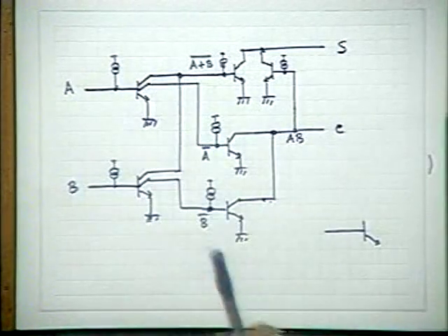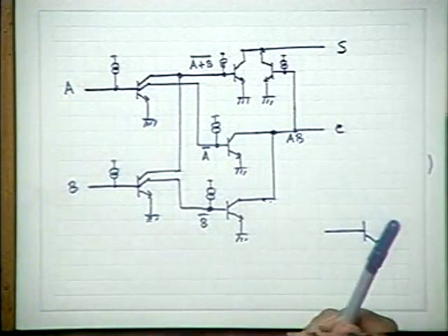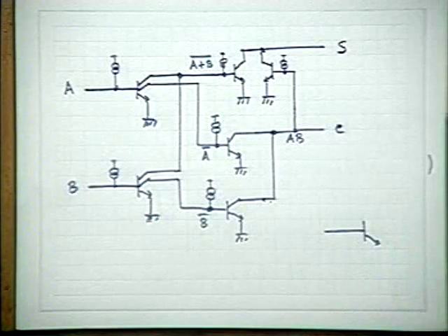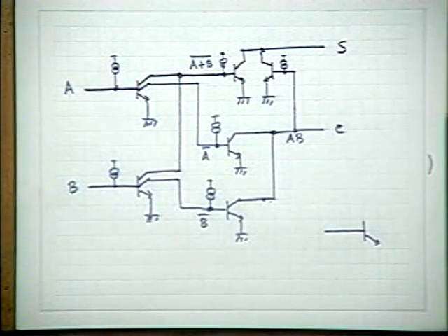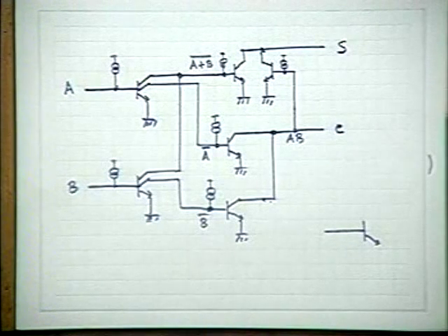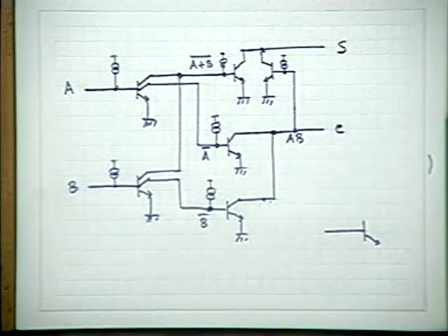You must feed a constant current, whatever way you generate. Normally, instead of bothering about that, we take a power supply and pass it through a series resistance. We control that resistance to adjust the current. That's the usual technique. But if I want a constant current really to be supplied all through, independent of time, independent of voltage, temperature, etc.